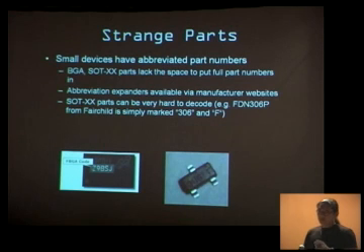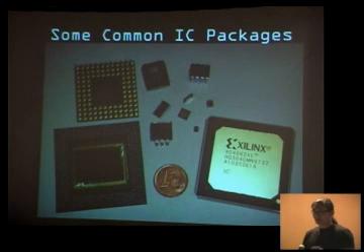For the very small, like, diodes and transistors, you just got to do a lot of guesswork sometimes. So what you do is read off the part number here. It just says 306 and F. The actual part number is FDN306P. And it can take a little while to sort of resolve it back, and there'll be some ambiguity, but usually it narrows your search space enough that you can eventually figure out what the part does by looking at its connectivity and so forth. In the worst case, you have to take the part off and put it in a tester and actually characterize it, but that's not going to happen.